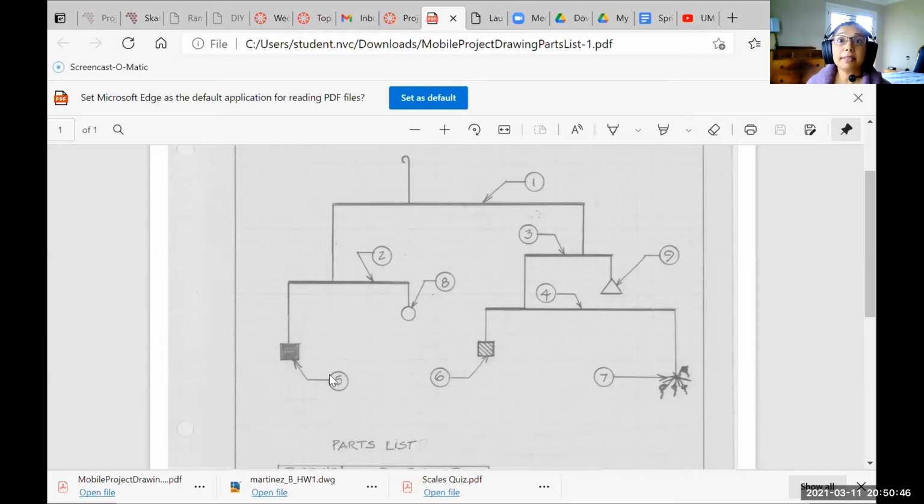This is an introduction to engineering drawing. This is how we do engineering drawings, actually, with part numbers in circles with leader lines. And this horizontal member, this one, and this one, and this one, they're all four different in this particular example. They're different lengths. They may be different materials.